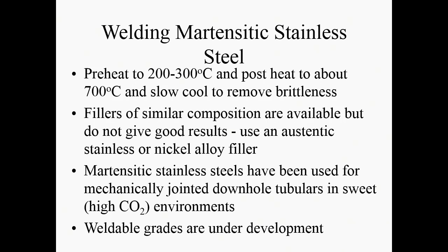Now, that isn't to say that martensitic stainless steel hasn't been used, but when it has been used, particularly in some of the downhole tubular constructions, it's often been with flanges and bolts to hold it together, rather than with welds. So in bolted joints, with an appropriate gasket between it, for very high CO2 environments, so largely in the sweet environments, there has been some use in the offshore industry of martensitic stainless steels. And I put this thing here, weldable grades are under development. I've been saying that for more than 10 years, and they're still under development.